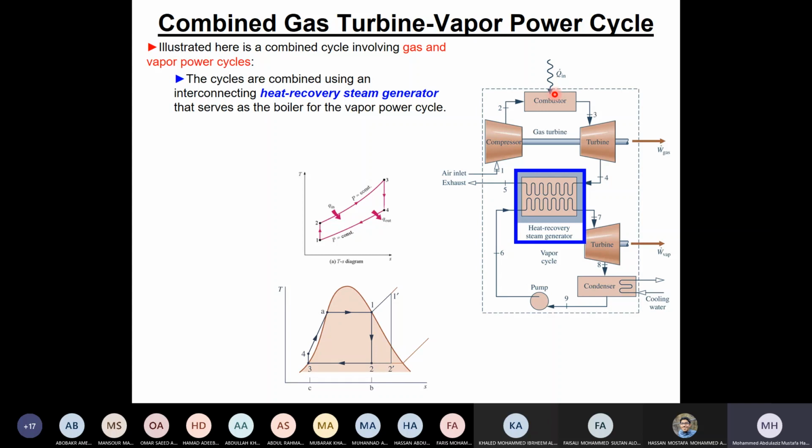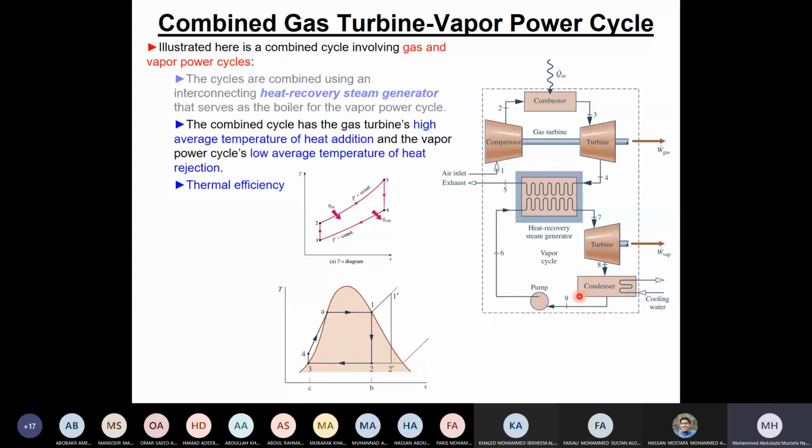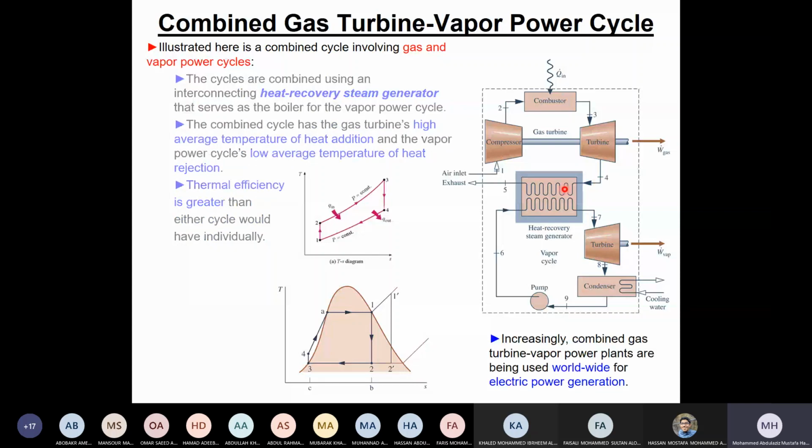So this is what's known as the combined cycle, and what we added here is what's called a heat recovery steam generator. So you solve this as normal as you have, as we have in chapter 9 and chapter 8. And then the only thing that's new here is how do you link the two cycles together? And this is done here in the heat recovery steam generator or waste heat recovery boiler. And this is what we see here. We just make an energy balance here.